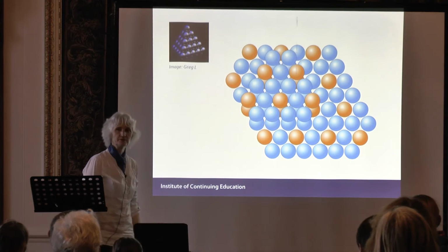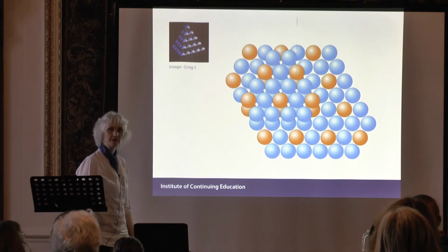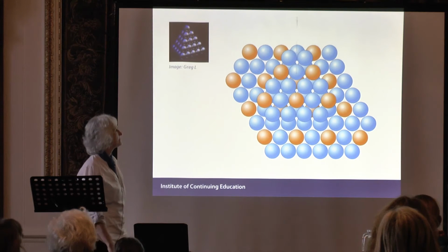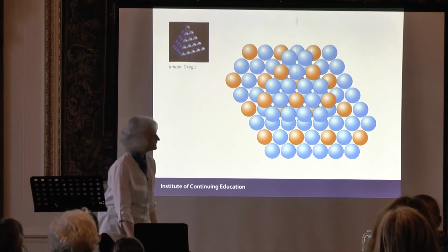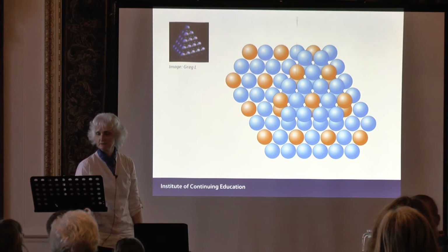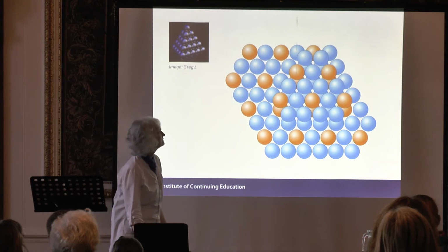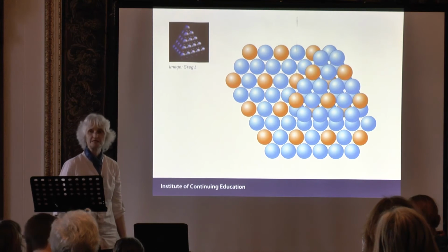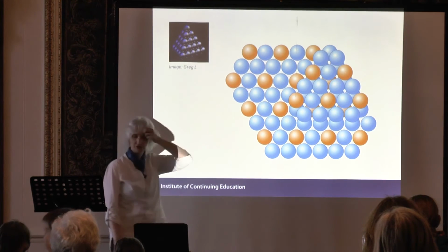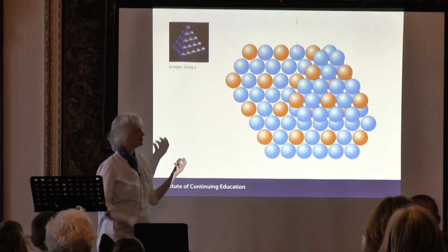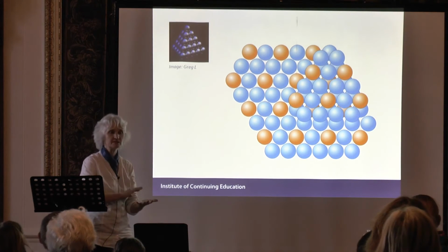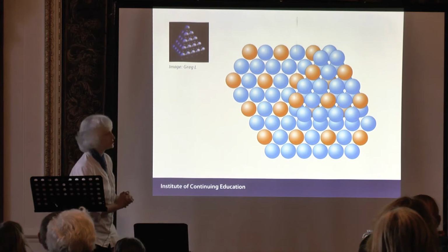That doesn't look so good. It's not very happy. It doesn't like that. It has to go 2 steps to get back to where it started. And the same again. 1 step to a place that's not so good. 1 step to a place that works. So in order to make a metal with this kind of ordered structure deform, what we have to do is make the atoms work twice as hard. In order to deform it, it needs to go 2 steps at a time, not just 1.